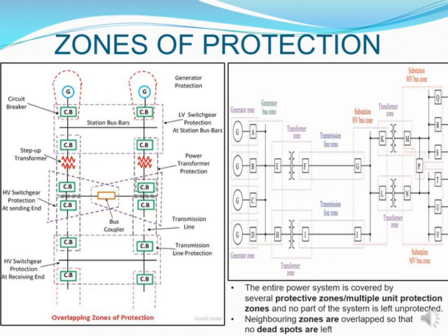In the generator bus zone, you can see that your A, B, C, and D circuit breakers will be there to protect that bus zone, as well as the circuit breakers on the other side, which are for your transformers, your E and your H, which can be utilized for that generator bus zone. So if you had a fault on this bus zone, all of those 6 circuit breakers must open up so that the fault can be isolated from your system.